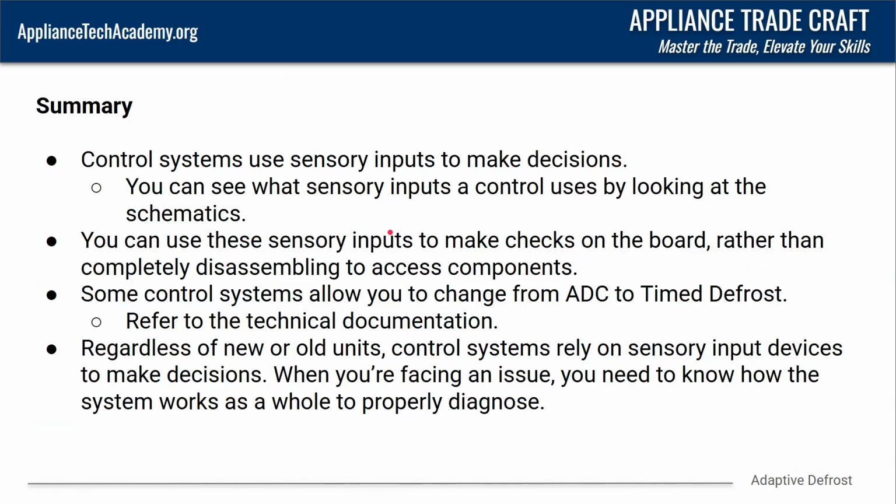So let's go find this last slide. Some control systems do allow you to change from adaptive defrost to time defrost. You're going to have to refer to the technical documentation for that. If your defrost heater is working, you're just seeing a little bit excessive buildup, then it might be a good idea to try to change it to time defrost. And then regardless of new or old units, control systems rely on sensory input devices to make decisions. When you're facing an issue, you need to know how the system as a whole works to properly diagnose it, or else you're just going to be throwing parts at it.